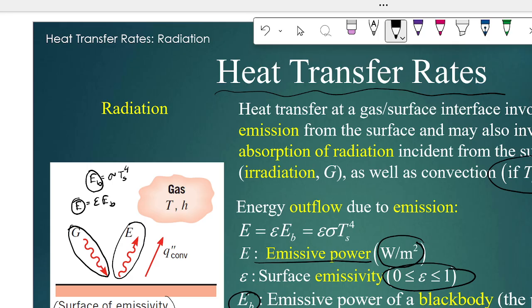That's the term you remember from thermal class? Thermal equilibrium means all the temperatures are the same, air temperature and surface temperature, except us. No matter what, we have 98 point something, so all humans are at 98 degrees. Nobody is here, so this surface and this air have the same temperature. In that case, no radiation. As you can see in the highlight, Ts is not equal to T infinity. Only in that case can radiation happen. But if T infinity, the air temperature, and Ts, the surface temperature, are the same, then no radiation. None of the equations apply, no radiation.